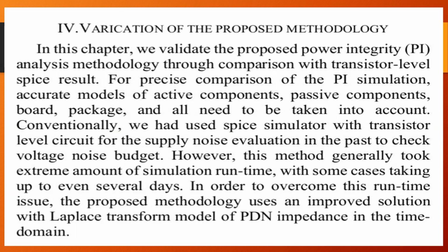Verifications of the proposed methodology. In this chapter, we validate the proposed power integrity analysis methodology through comparison with the transistor level SPICE result. For a precise comparison of the PI simulation, accurate models of active components, passive components, board, package, and all need to be taken into account.